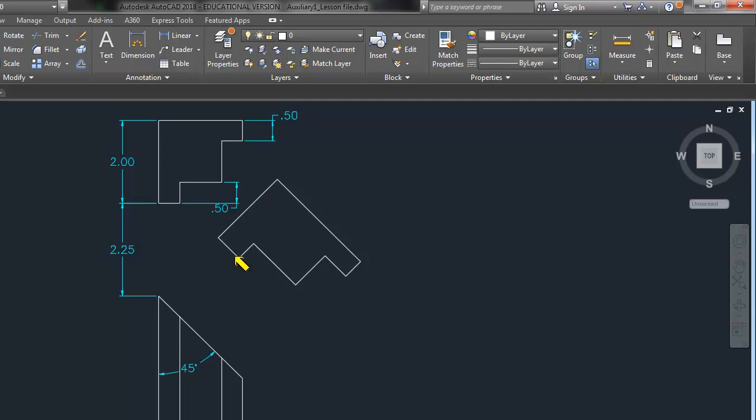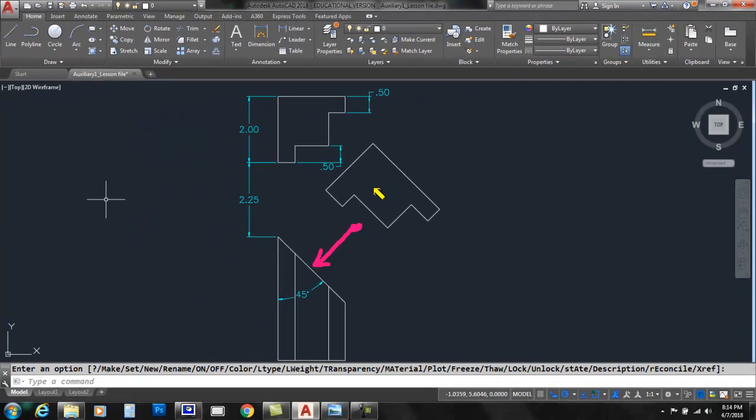Okay, so this shape is this surface in true size and shape. So if you were hovering up in space looking at that surface directly, this is what you would see. So if I had any design work I needed to do or careful measuring along that surface, I will now get an actual accurate result. Whereas if I tried measuring along on this, I would not be getting an accurate result. Okay, so there is creating an auxiliary surface.